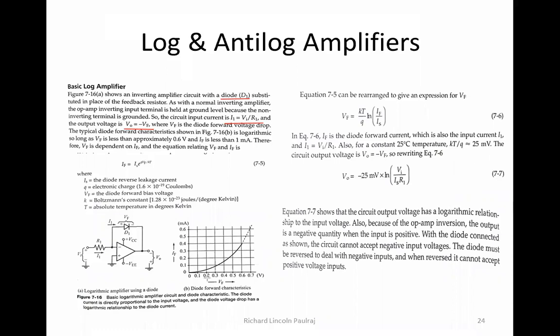If you recall, we were talking about the usage of BJT, where if our output current is less than 25 milliamps, we neglect the BJT and just use the op-amp and the associated resistors and ground and VCC potentials.